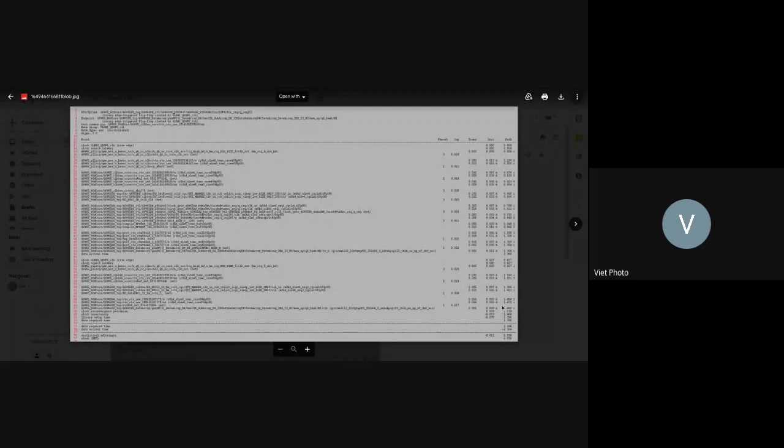In this case, the clock uncertainty is 53 picosecond. The conversion is at 38, so it's a minus 33 picosecond. Then the library setup time is 7 picosecond, that's this one. You guys know what it is. The setup time for the memory is 70 picosecond. So it's minus 396. And then you have the data required time at this one.